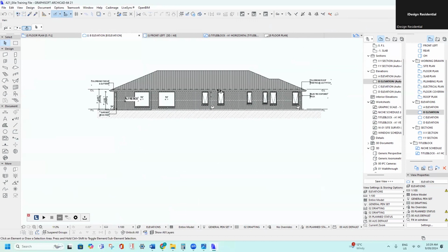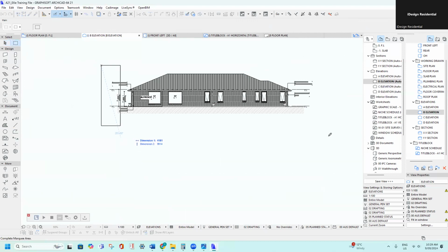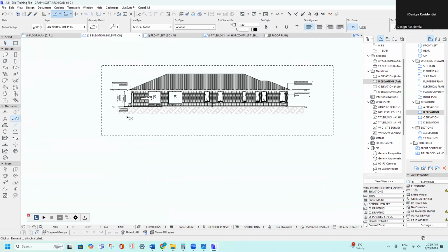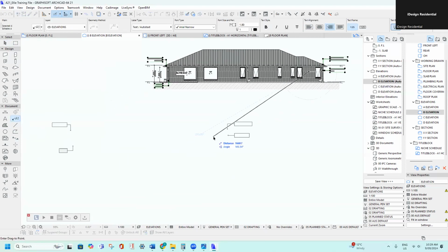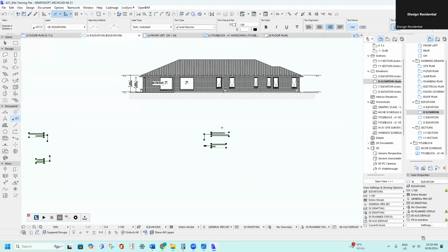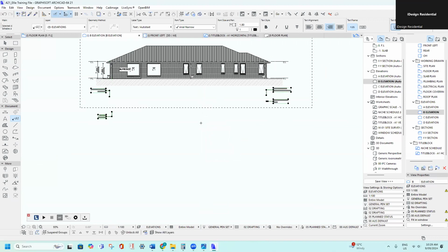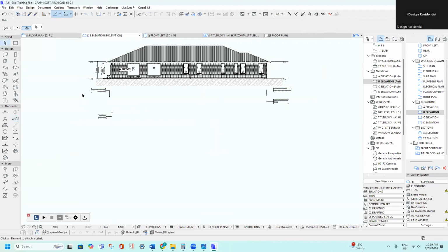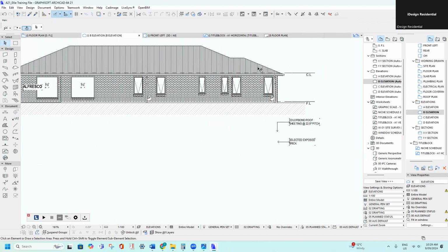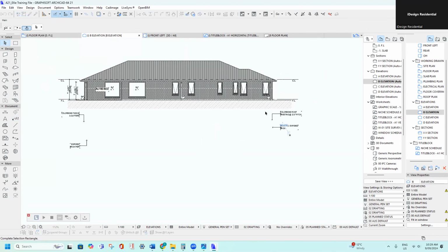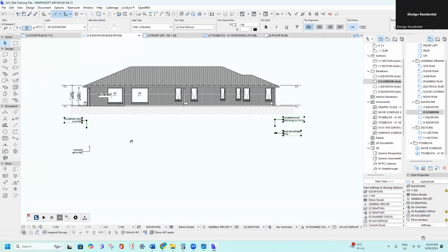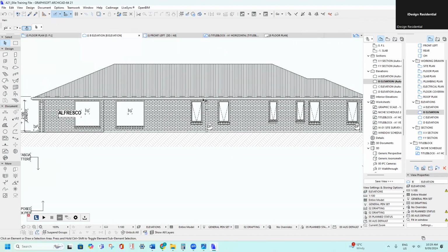Another way to do it, I'm going to remove these arrow notes, Control A, Control D, bring it out of the way. Control Z to undo. What I'll do is I'll Control D and bring it down, put 5,000 and enter. Because later I'm going to want to put them back up again. Just imagine these are not there on the page. You've got no arrow notes at all.